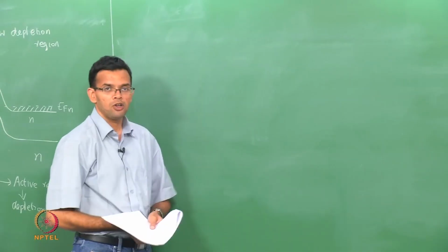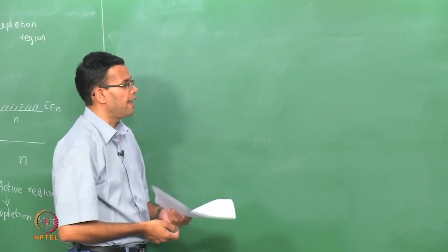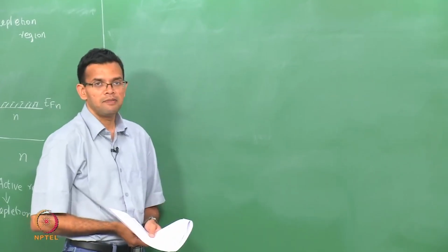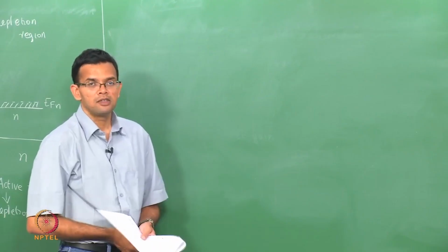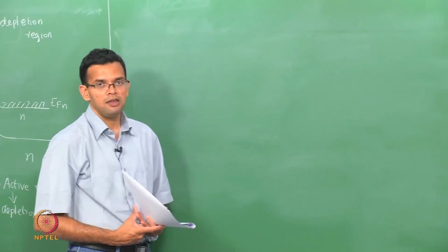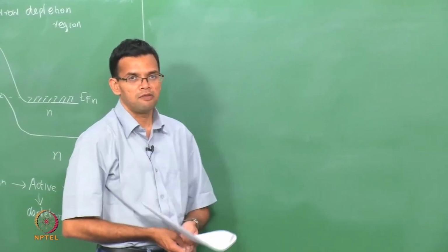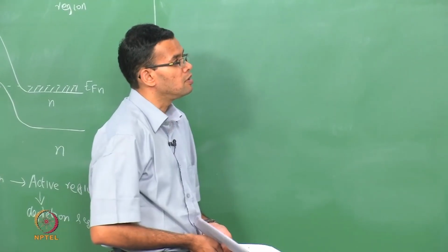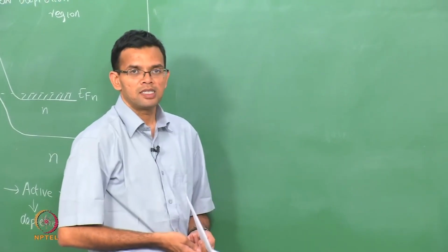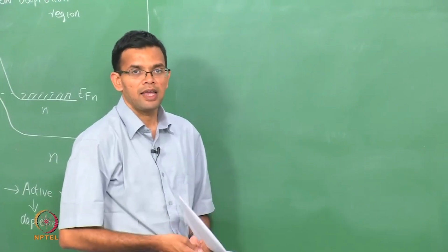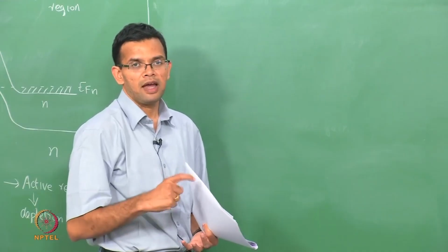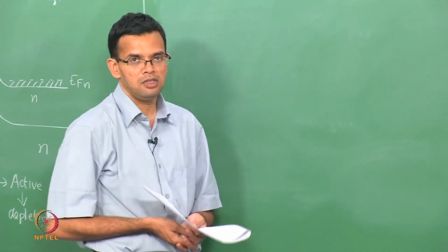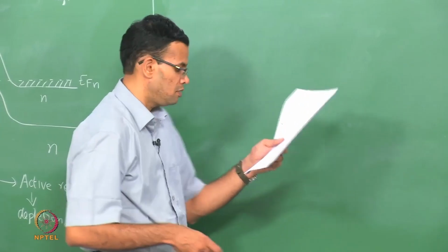So, we already saw earlier that we had a gallium arsenide, aluminum gallium arsenide based system. The advantage of that in the case of waveguiding was that total internal reflection is also possible, but aluminum gallium arsenide also has a higher band gap than gallium arsenide. So, this helps to confine the carriers within the active region, which is the gallium arsenide region.